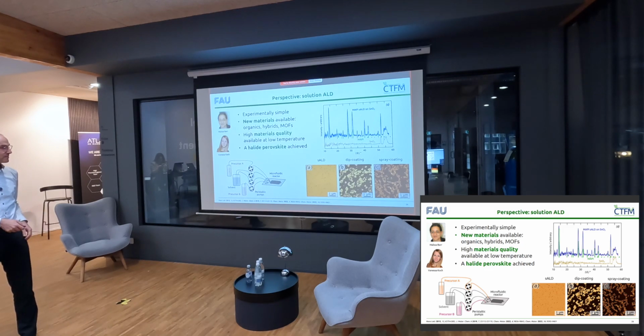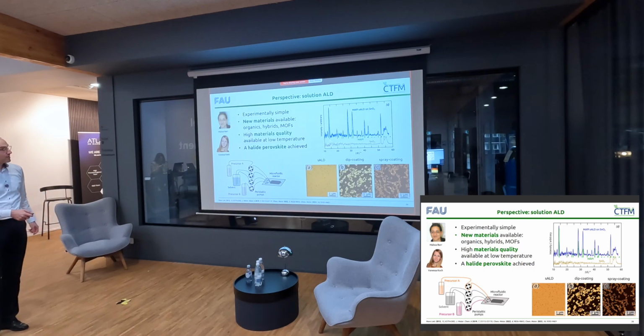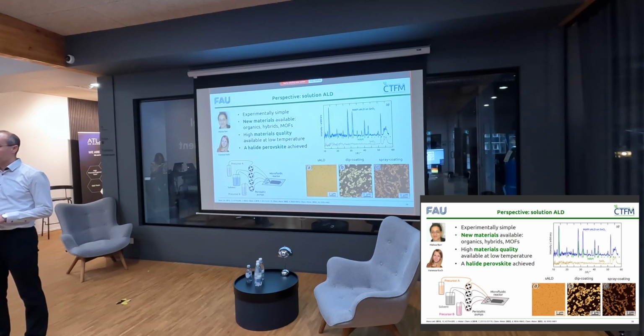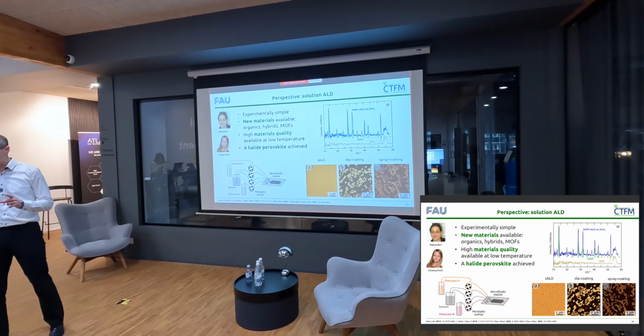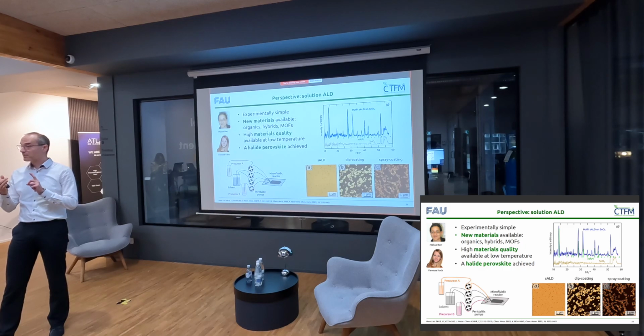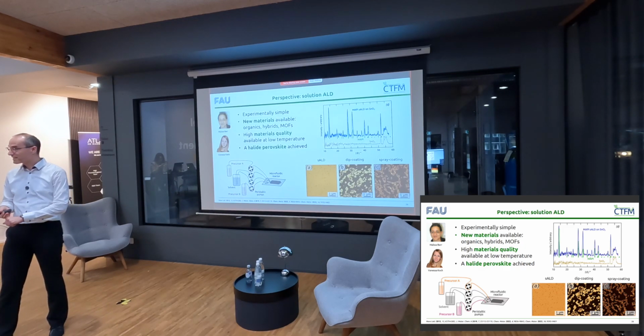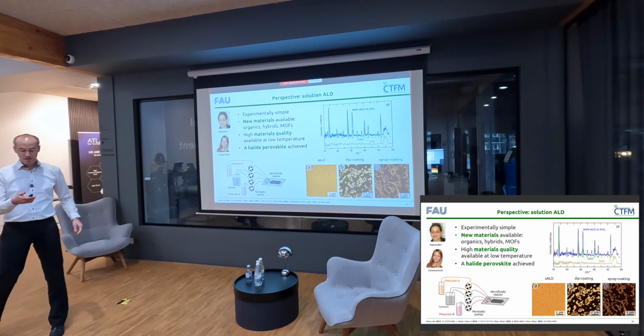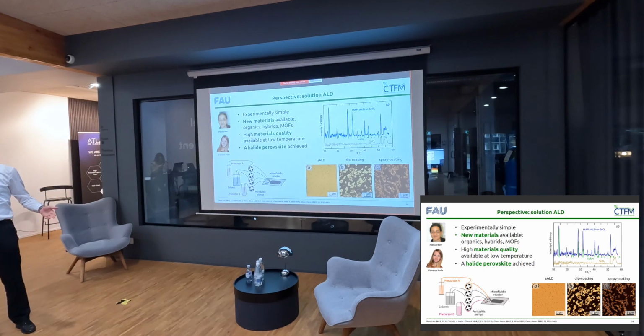We get crystalline MOFs in layers that are extremely continuous and thin and smooth, as opposed to what you get with other methods, which is really not a film. We've gotten lead halide perovskites in a level of quality that is significantly better than with solution processing methods. We've gotten very high mobilities and much higher carrier lifetimes than with spin-coated MAPI, and we've made solar cells.